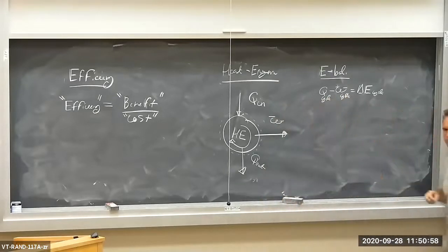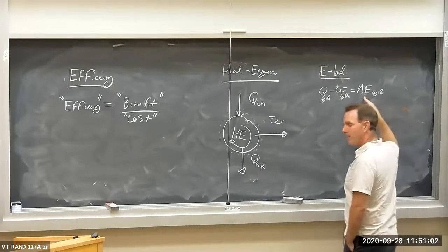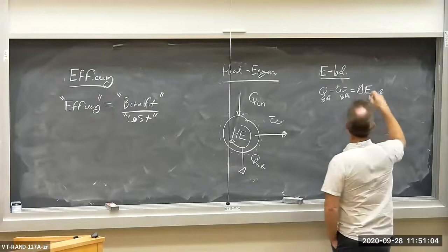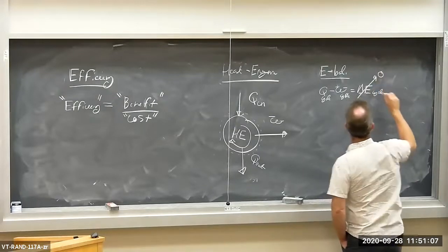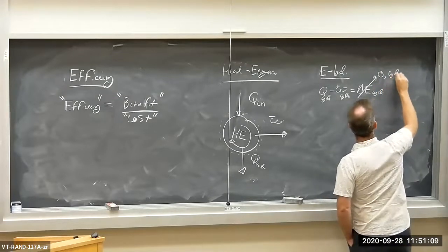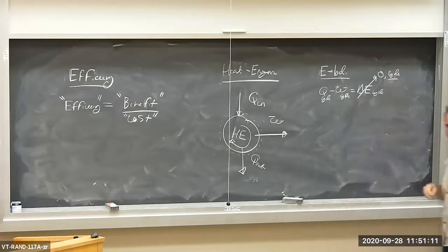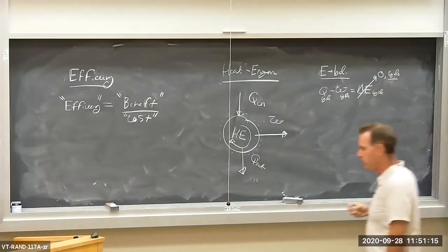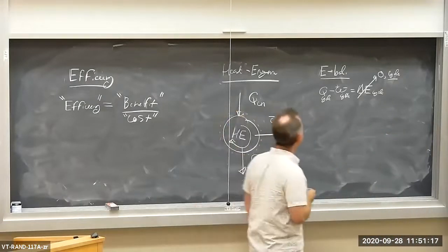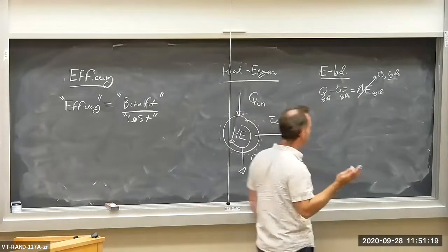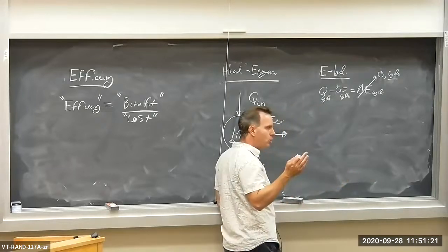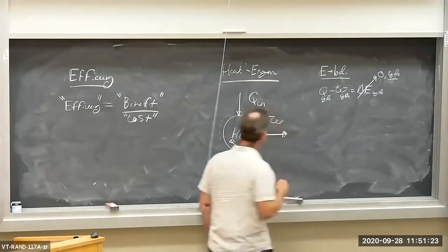So write cycle for the subscript on the energy balance. We know that change in any property, energy included, is equal to 0 over any cycle. So delta E is equal to 0. Heat and work are not properties. They're path functions. So they don't typically go to 0. In some situations they do, but in general they don't go to 0 over a cycle.